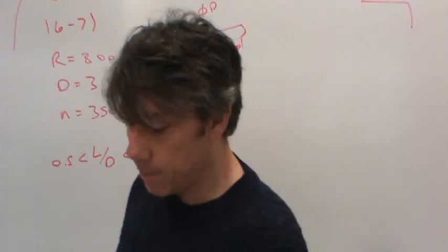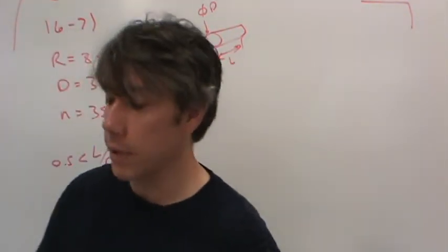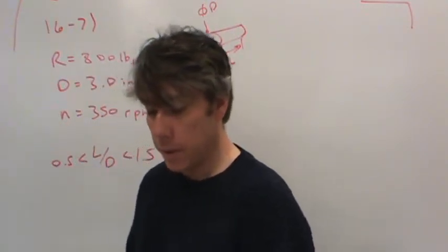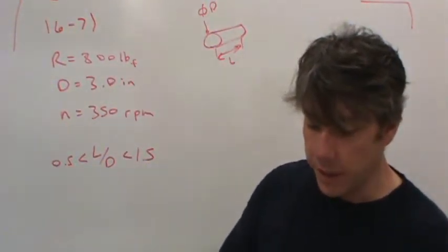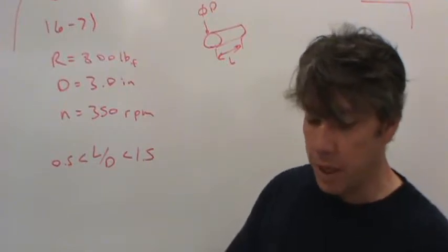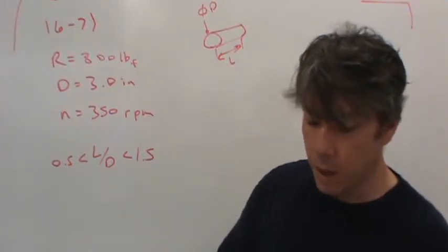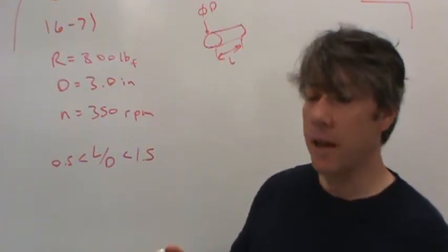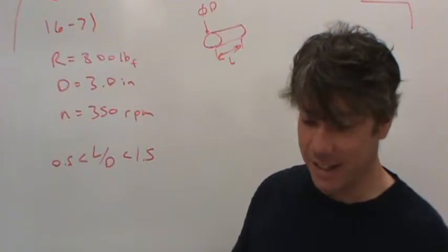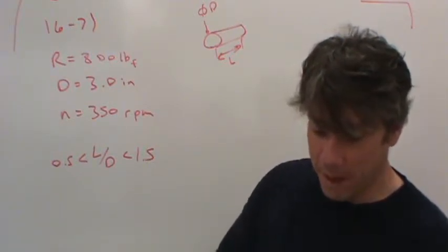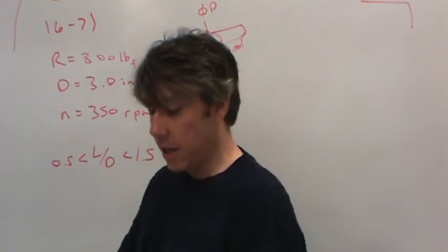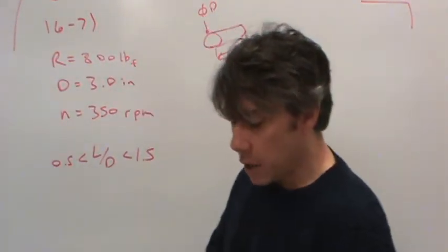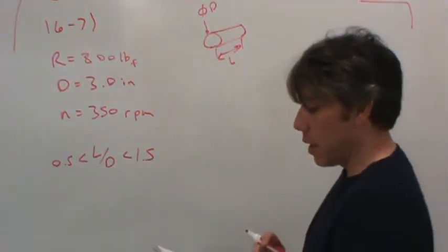There is a design procedure for this. It's on page 651. So I'm simply going to follow it. That's the easiest way to go through this. Given information: radial load on the bearing, speed of rotation, nominal minimum shaft diameter. Objectives of the design: to specify the nominal diameter and length of the bearing and a material that will have a safe value PV. Specify trial diameter D for the journal and the bearing.